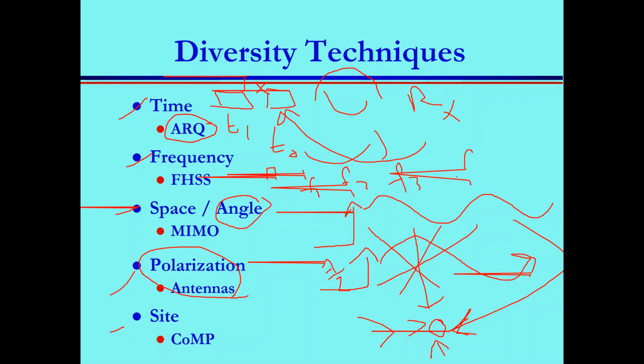In MATLAB, when you simulate your system, what do you simulate? Do you simulate the electromagnetic waveform? Not really. In CST, you simulate the electromagnetic wave. You see it because it's important for antenna. But in MATLAB, we simulate the voltage, the current that produces the electric field. And we usually have many types of polarization: linear polarization, circular polarization, elliptic polarization.